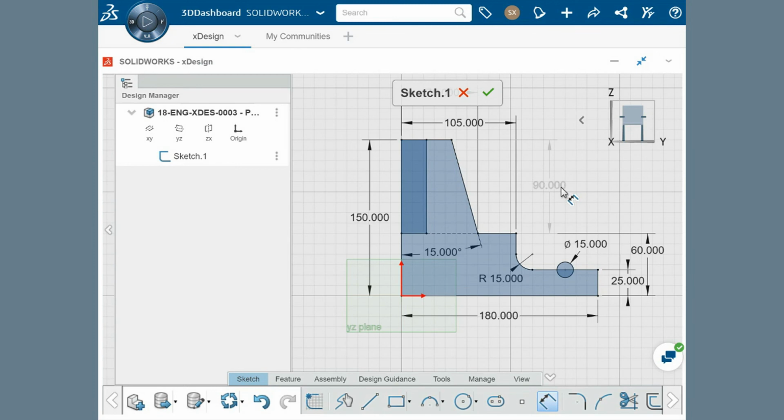I also can't set a value since the dimension is determined by the other geometry, currently coming out to be 90 millimeters. I quickly want to show you how you can set the total length of an angled line. I'll click on the angled line shown here, which will create another driven dimension. At first, the same 90 millimeter dimension appears, but if I move the mouse upward, the dimension shifts to be along the angle of the line, indicating its total length.